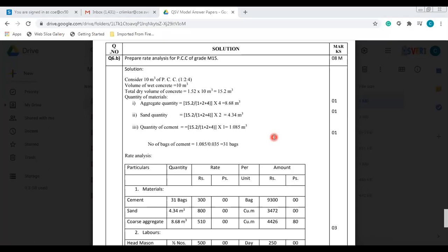You have to determine the quantity with respect to the sizes. Suppose for this slab, the length is 10 feet, width is 12 feet, and the thickness of the slab is 6 inches. Okay. So determine the quantity of concrete that is required. Only PCC, apart from reinforcement. Reinforcement we will discuss afterward. Reinforcement for this slab is around just 0.8 to 1%. So you can deduct that also.